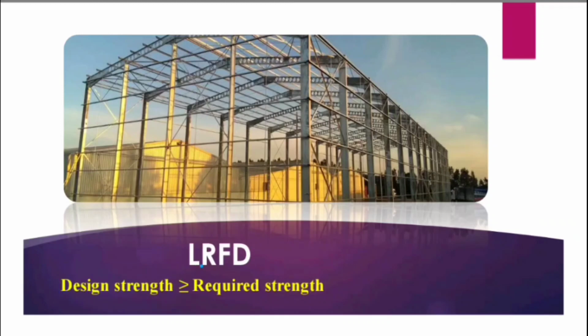It means we are amplifying the required strength and reducing the capacity of a member in a building or any structure, due to which this LRFD provides economical and safe member sections or other properties as compared to the other design philosophies.